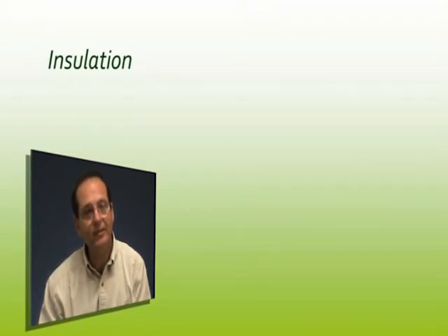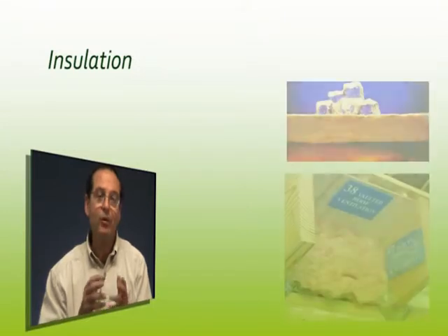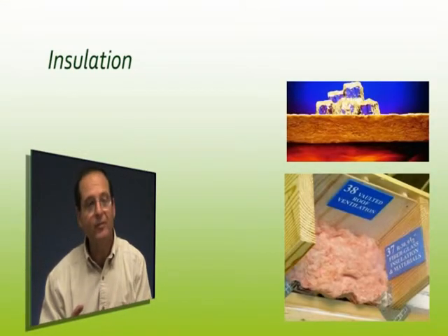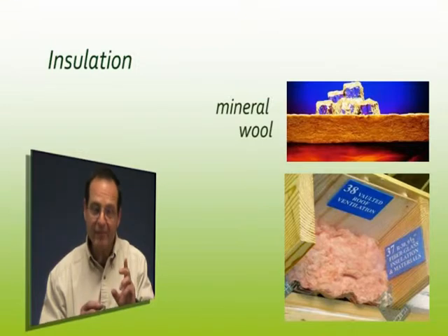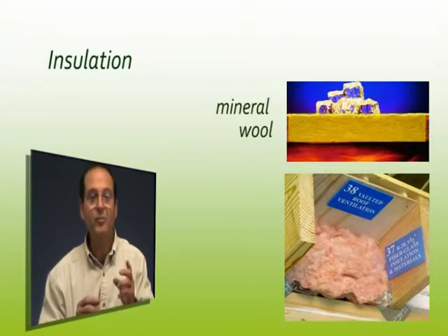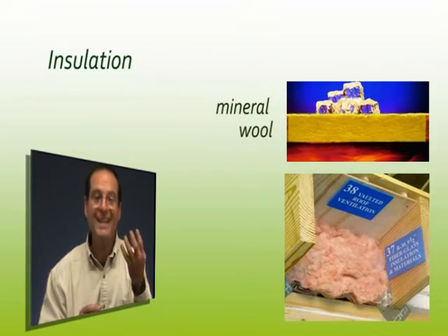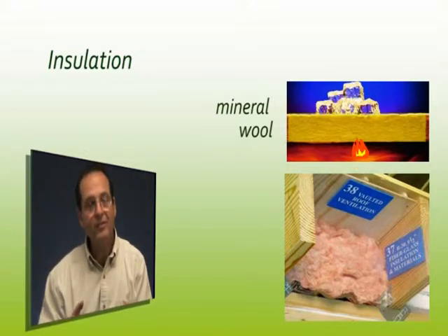Then there's insulation. Again, very specific. This particular system is mineral wool, and it's got to be 2.5 pounds a cubic foot. There's a couple different weights and varieties here, but as you can see in this picture, it's much more condensed. It's typically a thinner batt, maybe a few inches at the most. It's more dense, and it actually has the ability to prevent fire from coming up through the structure and from heating the elements above it and raising the heat. Common insulation, fiberglass insulation, doesn't cut it.